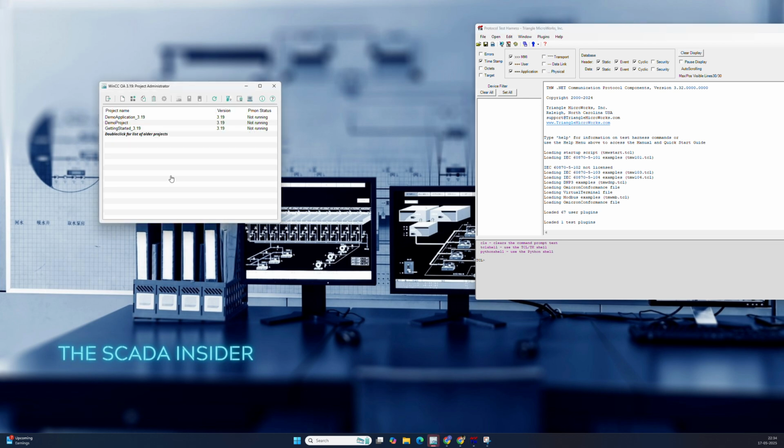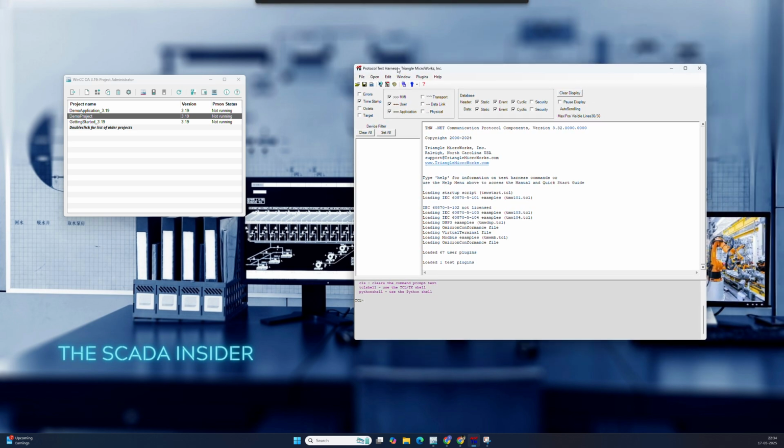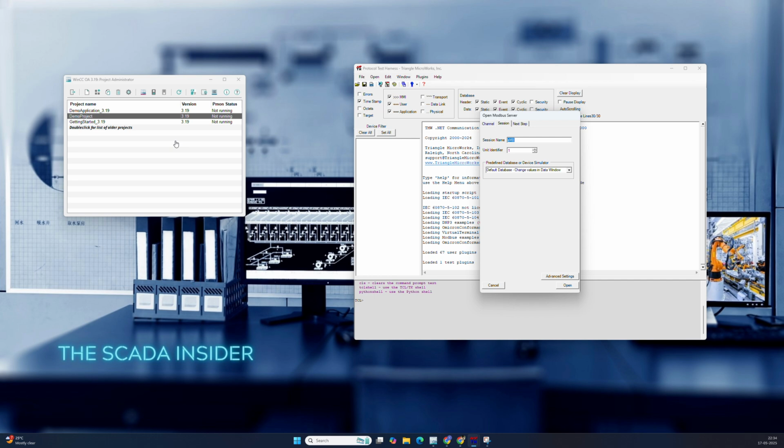In my previous tutorials, I've shown you how to create a demo project in WinCC. We will use the same project to communicate this simulator with WinCC SCADA. In this case, we are using the Triangle Microworks test harness, where we can create a simulator for Modbus. So how to create a simulator? I will go to this open channel option. I will select the protocol as Modbus, and as server, in this case, this Modbus simulator will act as a server, and our SCADA will act as a Modbus client.